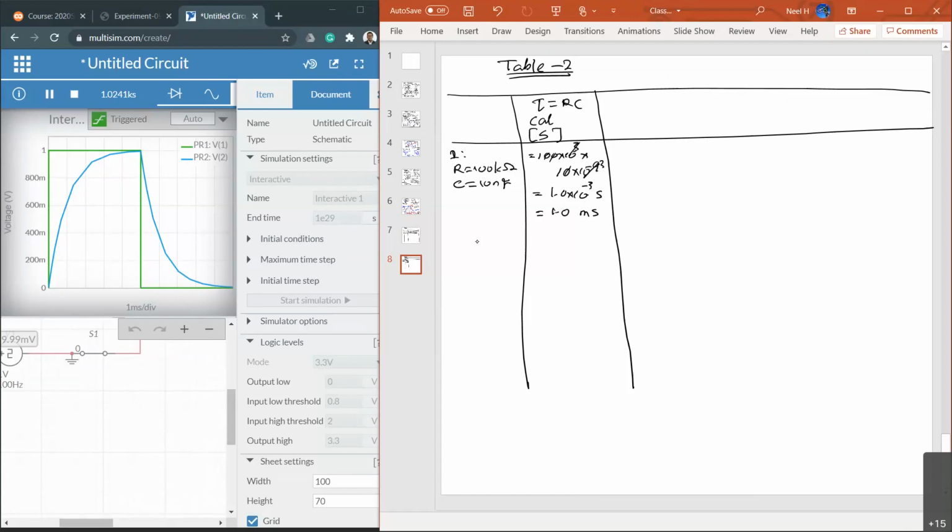Because we were measuring manually, we had to have a measurable time constant. But this one is extremely small. We can still do the experiment easily because the oscilloscope can measure any small time values, all the way to nanoseconds or even below. That's the other advantage. Okay, question.